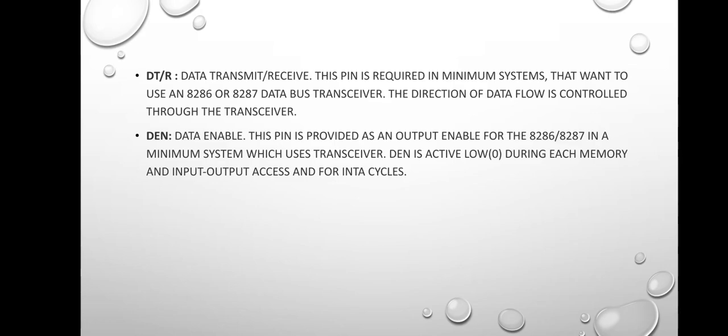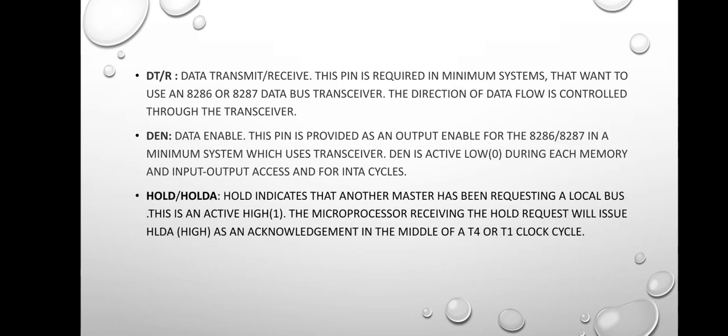And another pin is DEN, data enable. This pin is provided as an output enable for the 8286 or 8287 in a minimum system which uses a transceiver. DEN is active low during each memory and input-output access and for INTA cycles.